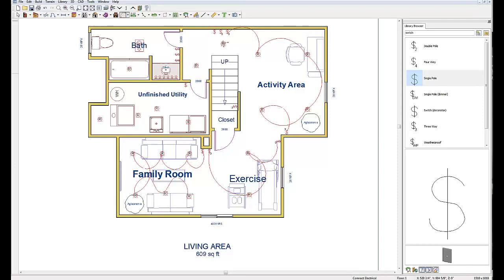At the bottom of the stairs, we're going to take the middle three-way switch to the light at the bottom of the stairs, up to the top of the steps, so we can turn the light on when we come up to the top of the steps and back off at the bottom of the steps. Three-way switch, that's code in stairways. This little single switch here is only going to go up to 1 light right here. I'm going to turn this light on here as we go over to our laundry room.